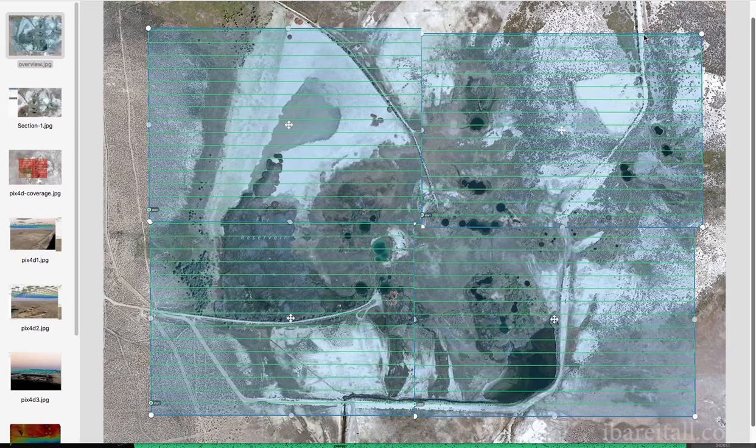So what ended up happening is after 4 of these sections, I ended up with almost 2,000 photos. Then you take those photos and run them through your favorite processing tool, which generates point cloud data, map data, elevation data, and vegetation data, among other things. So you can get quite a bit of cool information just from flying the drone overhead in a grid pattern and having these software packages generate data for you.